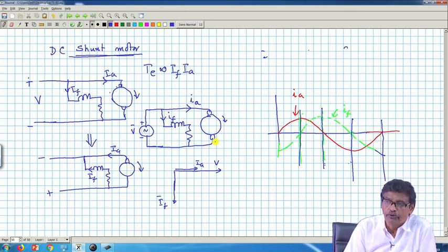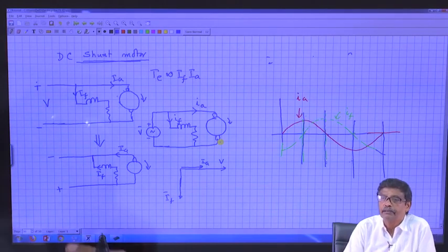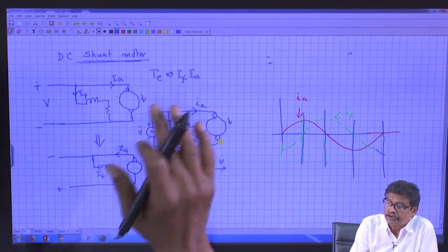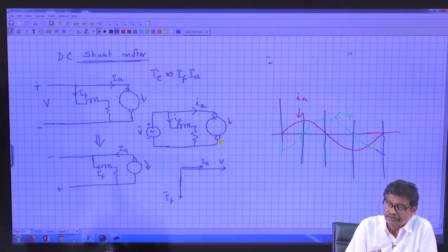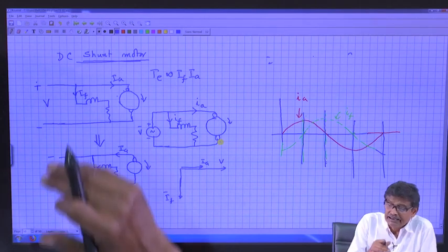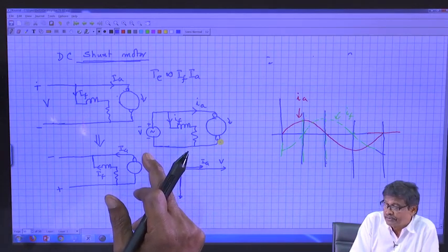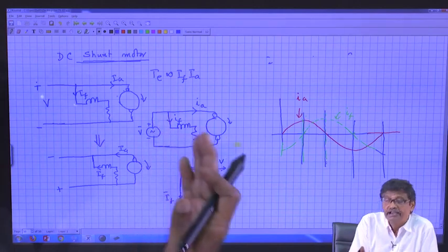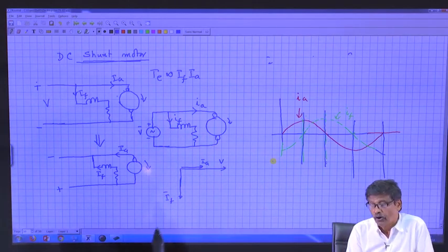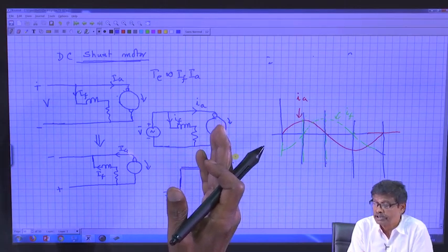So, for a shunt motor, somebody may think, knowing that if I reverse the supply voltage terminals the torque direction remains intact, that I can then energize it with AC voltage at 50 hertz and it should work. But it will not, because the field inductance is very large, or omega L is very large, in the field circuit compared to the armature circuit.